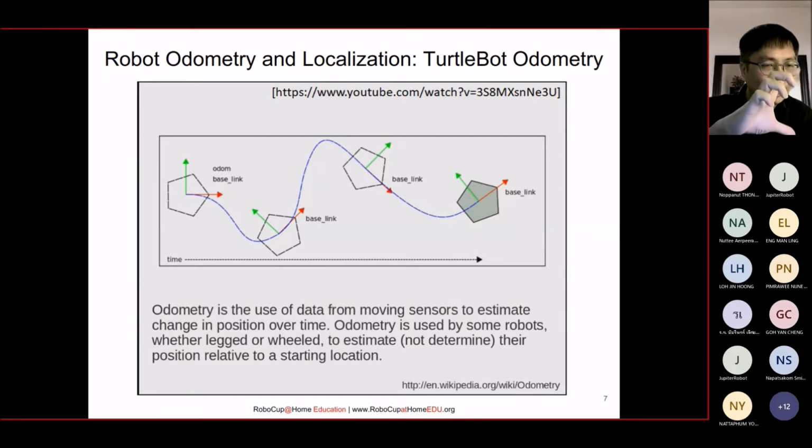You have the wheel and the traveling speed. With the wheel size, the radius or diameter, and the speed, you know how much it has turned. You can calculate the circumference and so on, so you know the distance traveled. By maths, you can calculate that. Doing that calculation is what we call odometry.